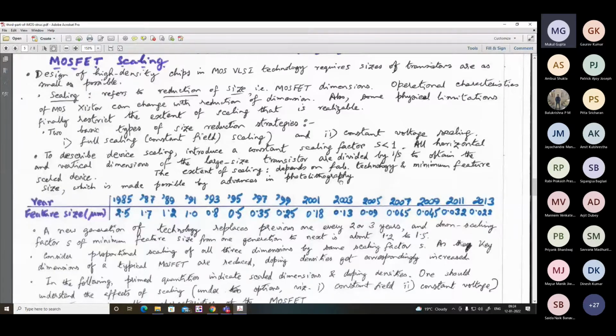That means how good the diffusion furnace is, how accurately you can do it. Say you need to make n plus equal to say 10 to the power 19 per cc. So accordingly, the furnace has to be set up. So both fabrication technology and the advancement in photolithography will matter, and these two things together have made the scaling possible.